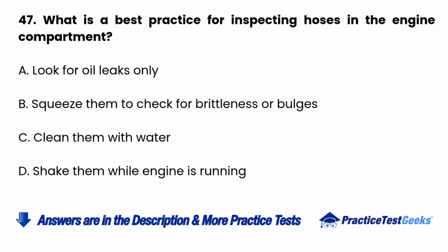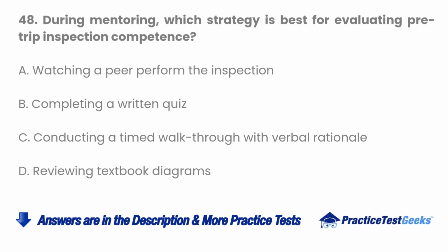47. What is a best practice for inspecting hoses in the engine compartment? A. Look for oil leaks only. B. Squeeze them to check for brittleness or bulges. C. Clean them with water. D. Shake them while engine is running.